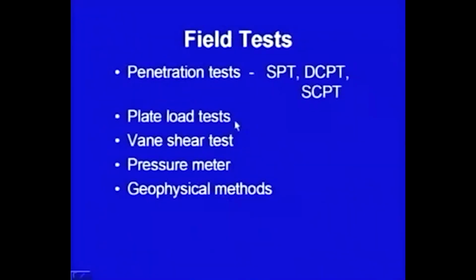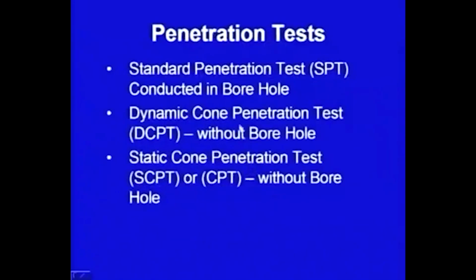Let me start with the field tests. We shall be discussing the penetration test, plate load test, vane shear test, pressure meter test, and geophysical methods. The penetration test will include three types of tests: standard penetration test, SPT, which is conducted in a borehole. A borehole is required for this test.